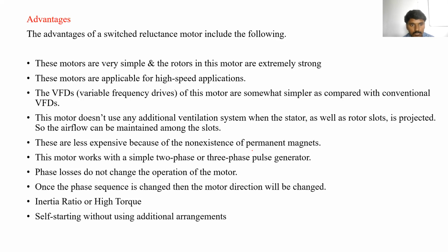It can work with a two-phase or three-phase supply. Phase loss does not change the operation of the motor. Once the phase sequence is changed, the motor direction changes. This is also an advantage, because if sometimes by mistake the phase sequence changes and the motor is not rotating, then what will happen? The motor is going to be damaged.